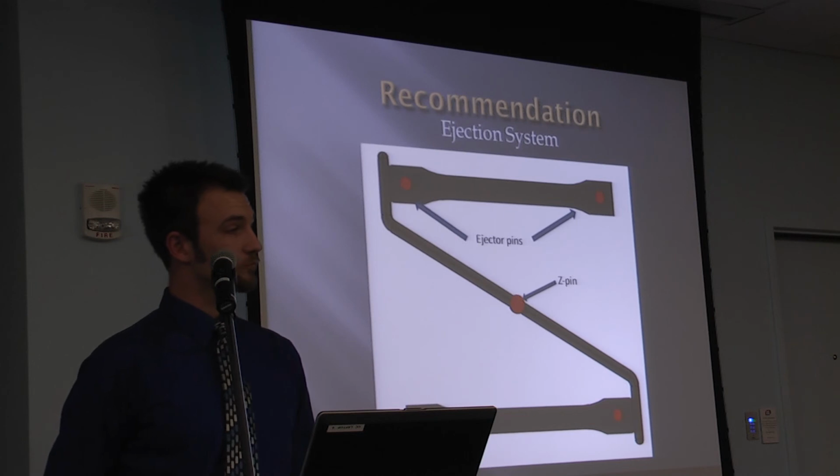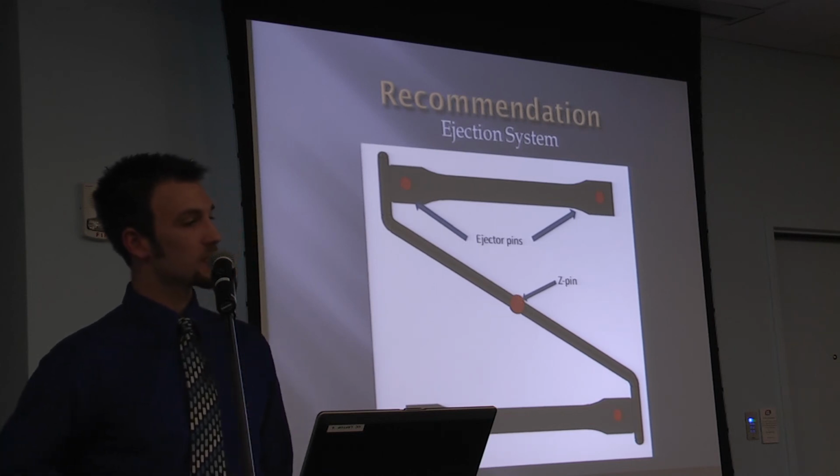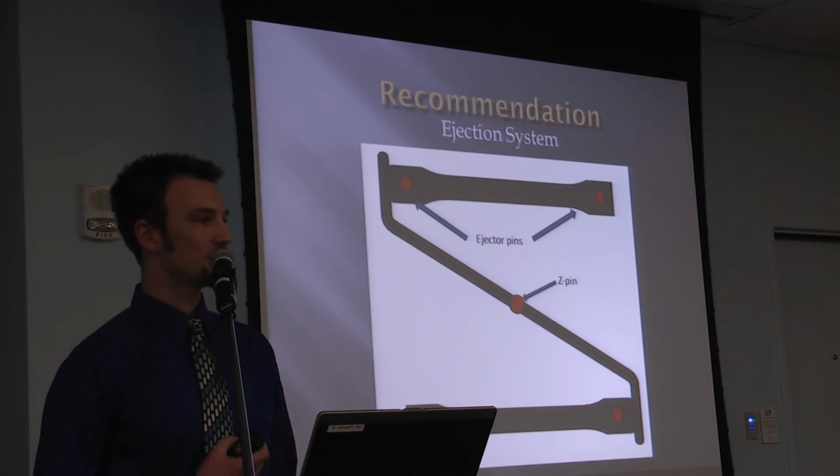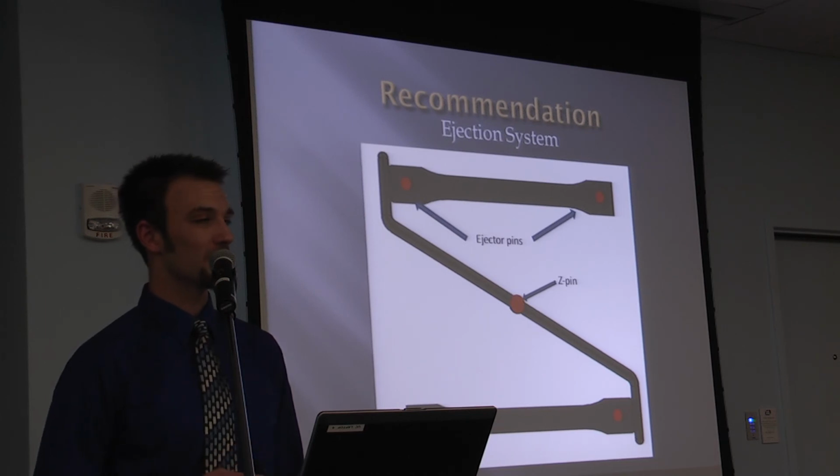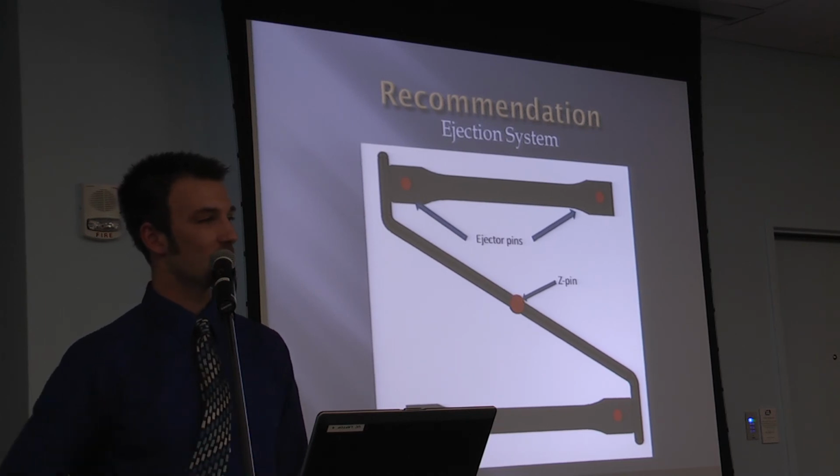Can you add them after the mold's made? Yes, it's an often practice in injection molding to change the venting location depending on different issues that they may be having in the process.